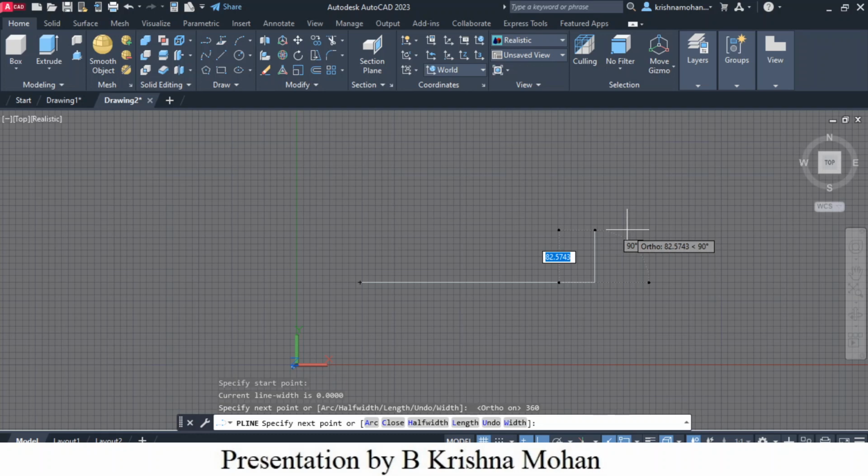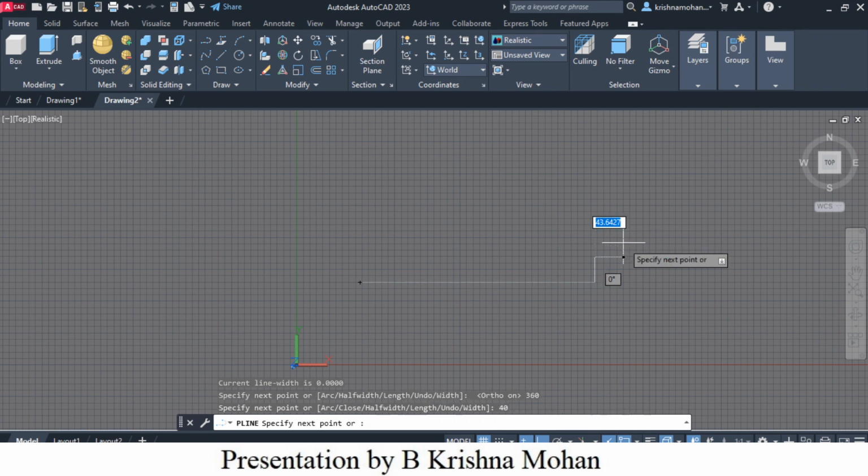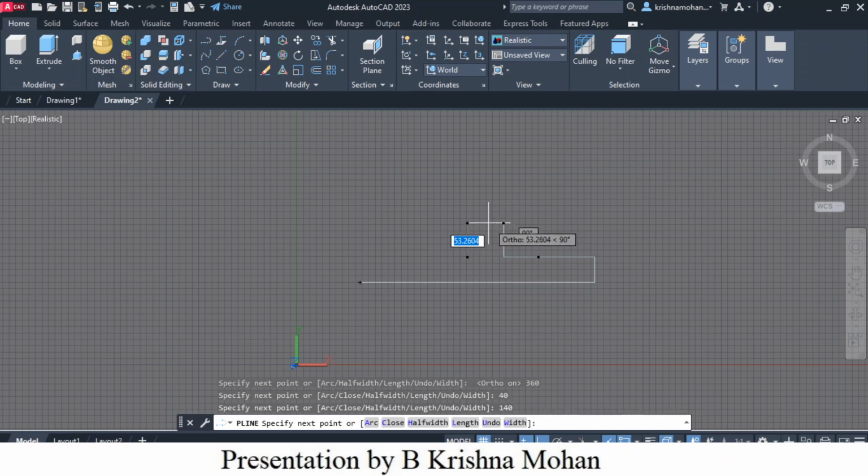The smallest diameter is 80, so the radius should be 40. Enter. Then move along this direction about 140 mm. Calculate from the drawing; it is clearly represented there. Then I want to move 10 mm along this direction. Let's move about 40 mm. So create those steps. From the drawing, you can clearly observe them.